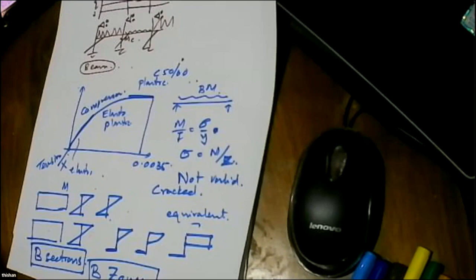We thought, okay, let's look at it differently. Generally, you all know the socketing recommended is 1 meter minimum. Otherwise, the diameter of the pile is the socket length. That is the general rule. So if it is a 600 millimeter pile, you will socket it 1 meter. If it is a 1200 pile, you will socket 1200. If it is a 1500 pile, you will socket 1500 millimeters.